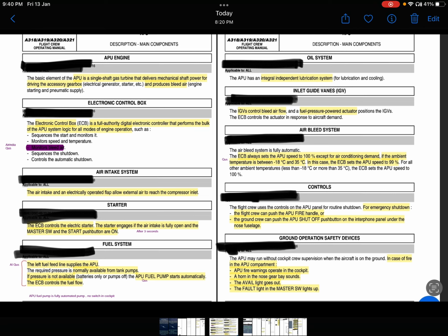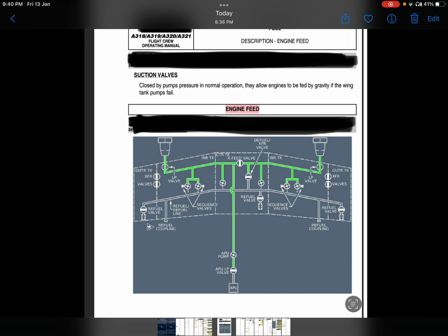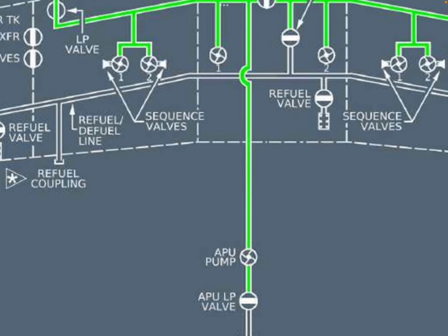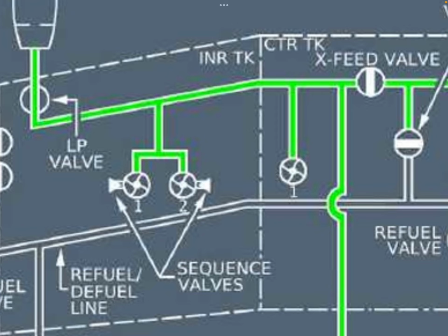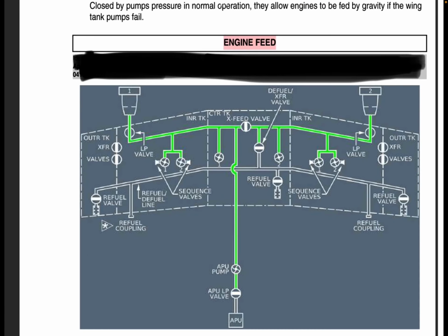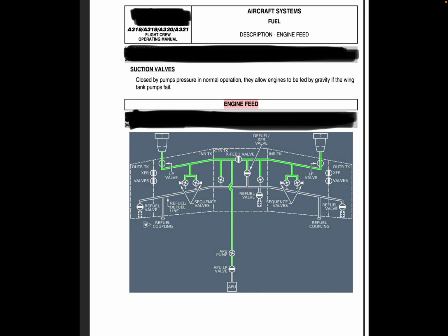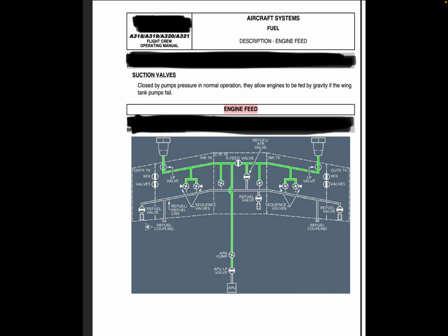Very important. There is no switch for this APU fuel pump. For other pumps, wing tank pumps and center tank pumps, we have controls in cockpit, but for APU pump we do not have.